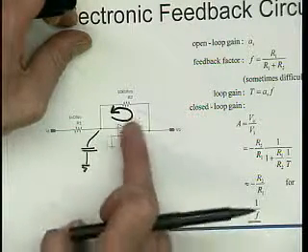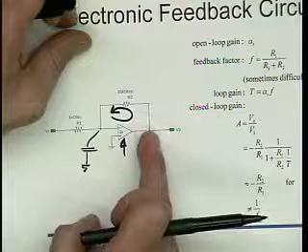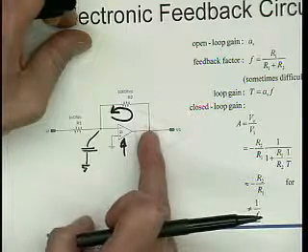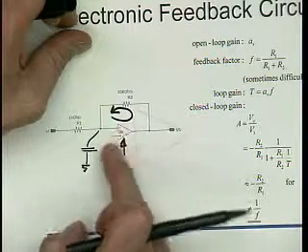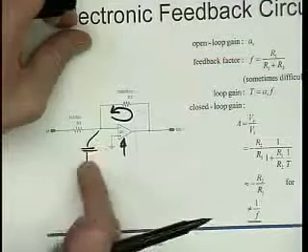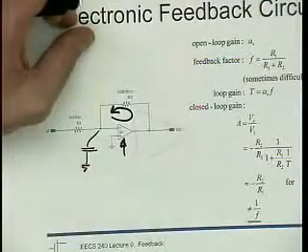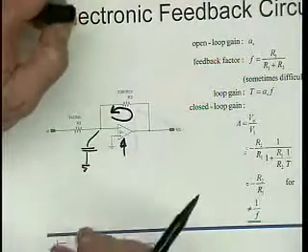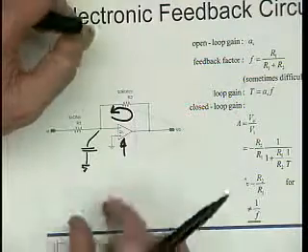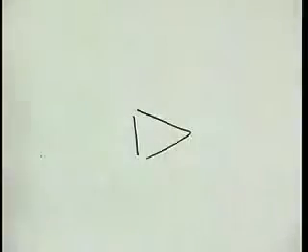So now I have the dominant pole that probably comes from the output if this is a transconductor. I have the non-dominant pole of the cascode here, and I have yet one more non-dominant pole. Well, depending on where they are, two non-dominant poles is a little bit a lot, right? And this may then go unstable. So unity gain stability is sort of a worst case, but not really.